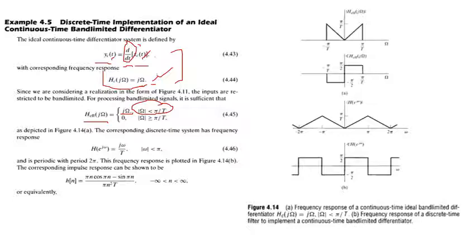So we know that we can draw this. You can draw the magnitude of this and phase of this. This is an imaginary value, so you just need to ignore. We know that magnitude is equal to square of real plus square of imaginary whole under root. So the only value unknown is omega. So if you put the value of omega starting from 0 and go up to the limit pi by t. So this final point will be pi by t, and likewise for negative 0 and go to minus pi by t, this will be this.